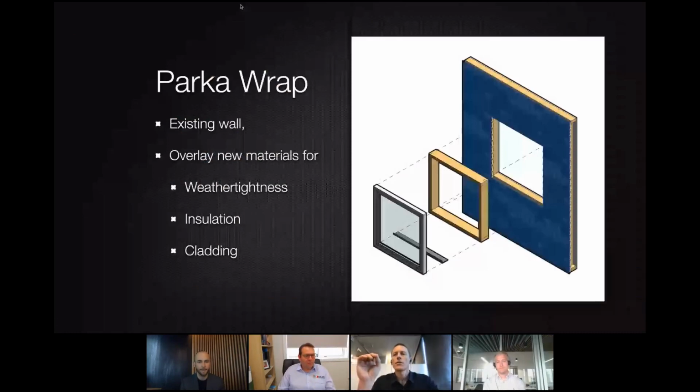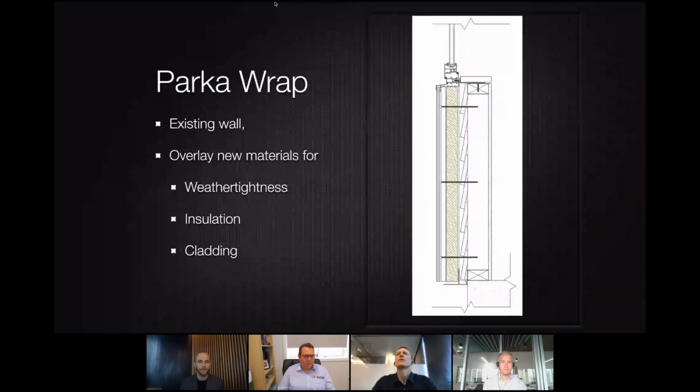There's either a subframe that you would put into the window opening as a new window opening, or you would use a back dam, the piece of bent aluminium or steel there, but that's still inside the thermal line, so you're not actually breaking up the thermal line on that insulation as it comes around a window. That's a thermally broken window. There's much more detail in there if required, but that shows you the line of the double glazing unit. When that's in line with the insulation, the performance is pretty good thermally.